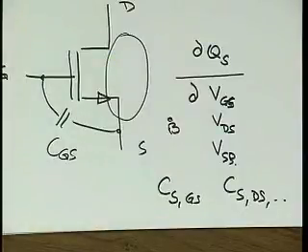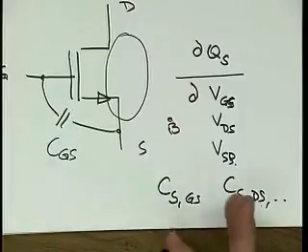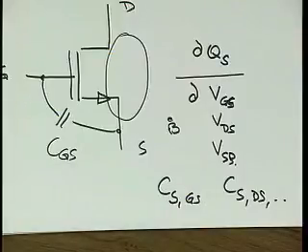And the big problem is that SPICE internally ends up inventing or destroying charge. Now, since the 80s, when we started doing all these switched capacitor charge sampling circuits, that became just a total nightmare. I remember when I did my PhD thesis, I ripped my hair out because it was a switched capacitor circuit, but SPICE wasn't up to the task yet, and the results were just totally non-physical.